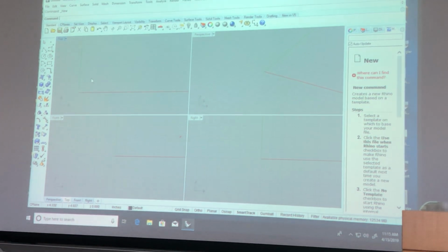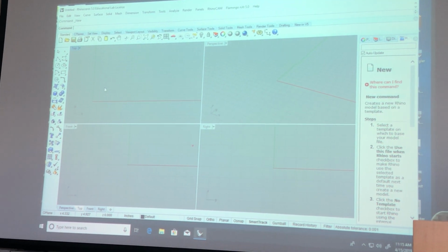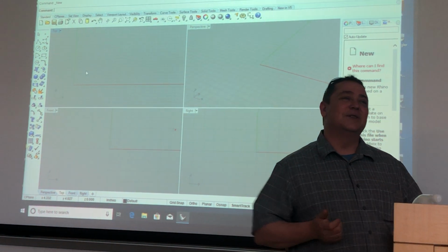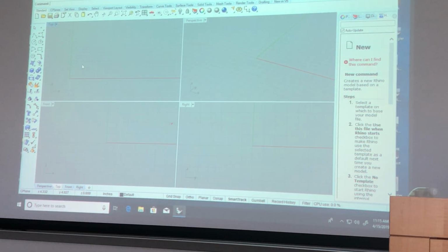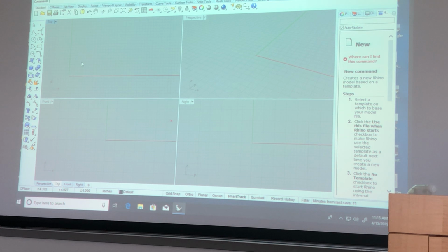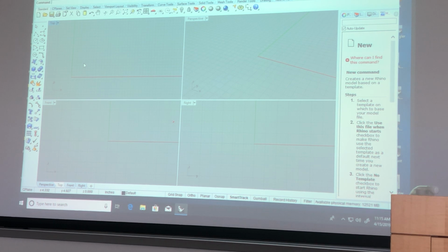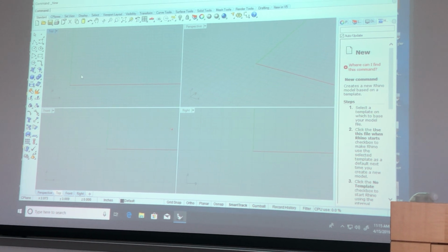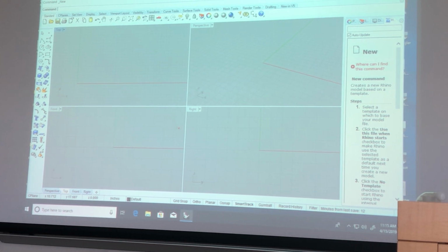So you're going to be able to bring your SketchUp file into Rhino, and you'll be able to scale it in SketchUp and import it into Rhino. Rhino will import your SketchUp model. You will need to save your SketchUp file as a SketchUp 8. So you'll save a copy of it, and where it asks you for the version, you'll need to choose SketchUp 8. If it's any newer than that, Rhino will not import it. You're not going to lose anything. No program has really changed anything significantly since like 1998. It's still there. And really all you need is the mass of your building.